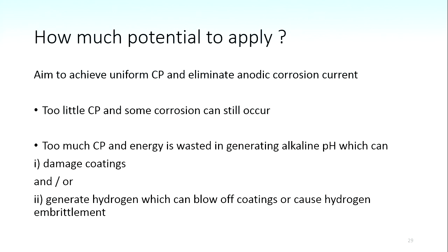Basically, for onshore measurements, most of them are done against the copper-copper sulfate electrode, and for offshore measurements, most of them are done against a silver-silver chloride electrode using seawater as the electrolyte. And the potentials for those I've actually written here against the standard hydrogen. There's the copper-copper sulfate down this side here. And so if you had that on an earlier handout, I can get you another one if you want it.